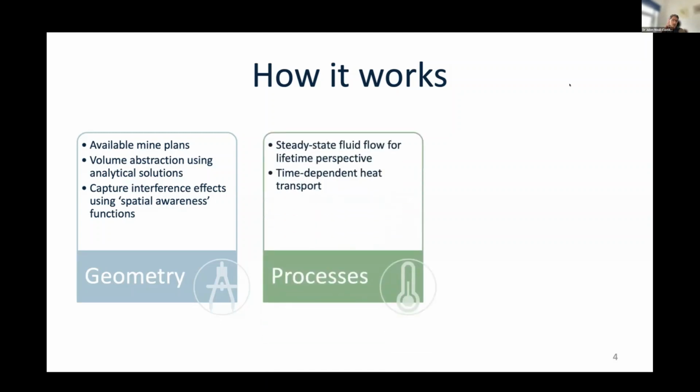And then the other element is that we're looking at the whole lifespan of the project rather than short-term behavior. So if you look at the whole lifespan of the project, it's reasonable to assume steady state flow. And then on top of that, you can overlay time-dependent heat transport to evaluate how the temperature is going to change in your system throughout the years of the site's life.